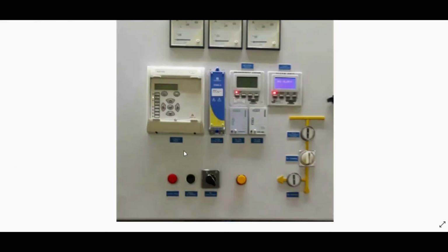Let me show you these two devices, the protection relay and the test block, in the picture. This is the protection relay. Its type is P127, and this is a test block or test switch. The usage of the test block is just for testing of the protection relays by the commissioner, nothing more.